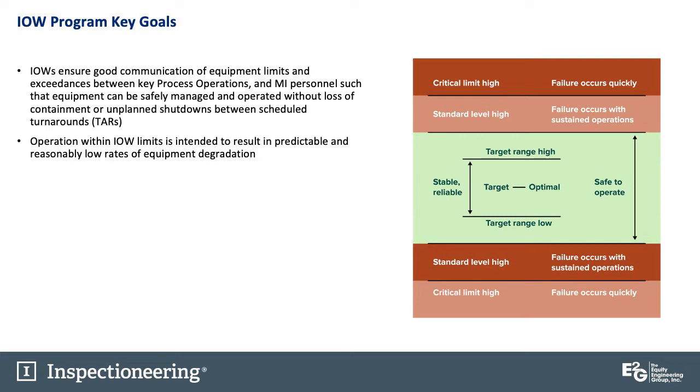Another key point about IOWs is they are meant to ensure that IOW limits are intended to result in predictable and reasonably low rates of equipment degradation, not zero. There is going to always be some equipment degradation that inspection groups need to stay on top of. So our goal of zero degradation is unrealistic in modern refineries.